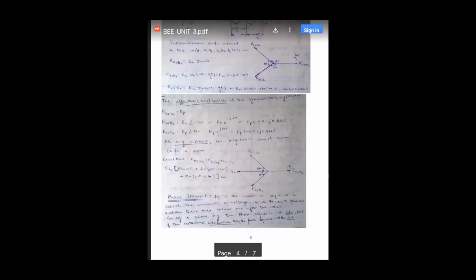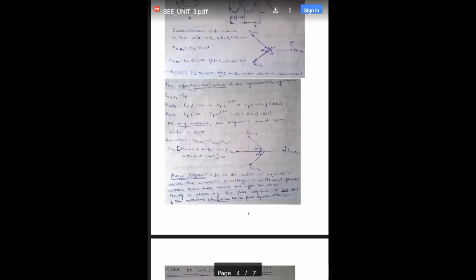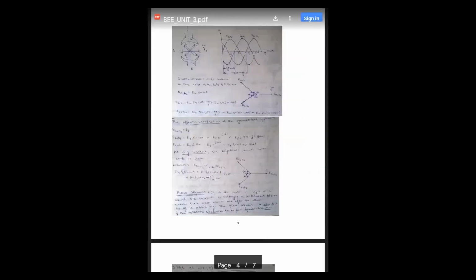Okay, so in the balanced system the resultant is 0 because, say this magnitude is 1, then this is also 1, this is also 1, but now the angle between them is 120 degrees, so the angle between them and the negative of the x-axis will be 60 degrees.